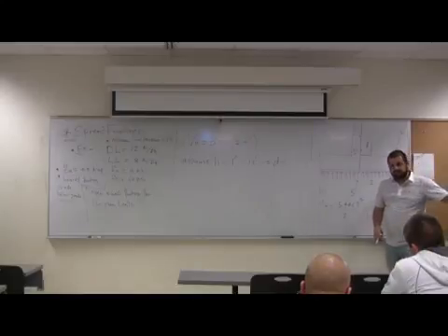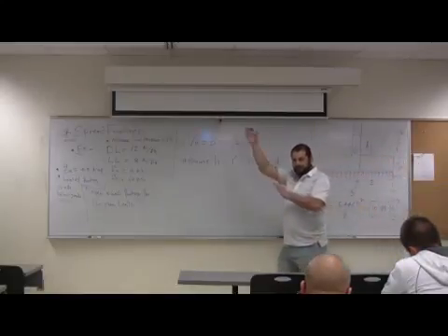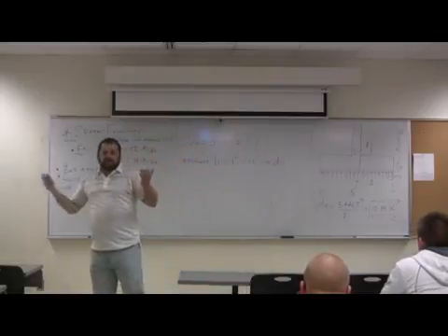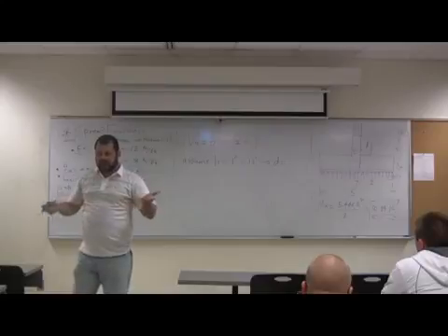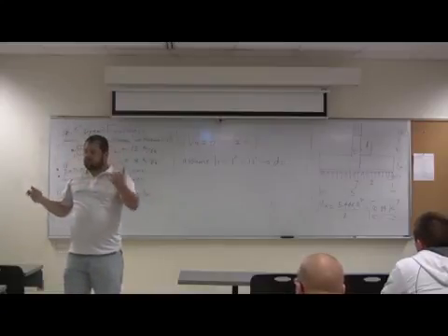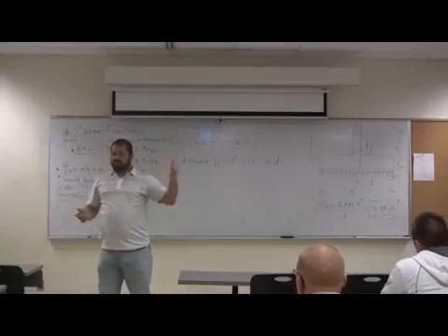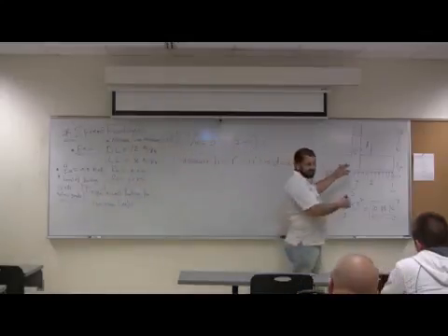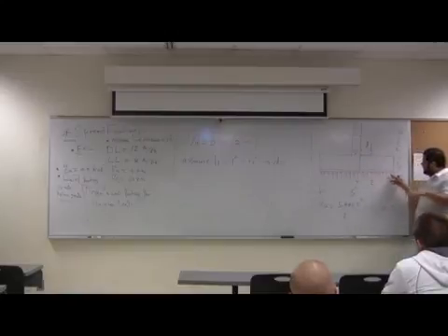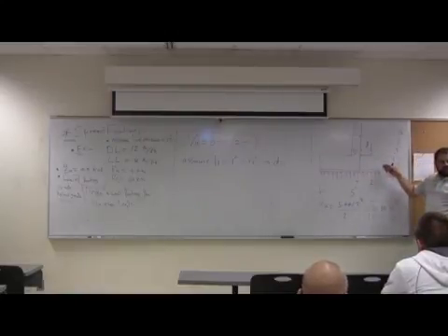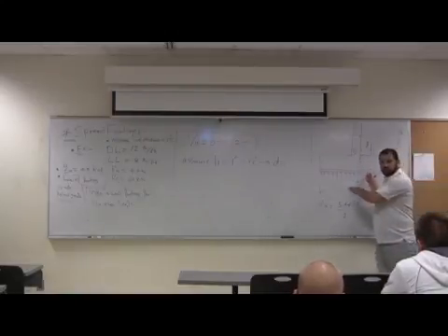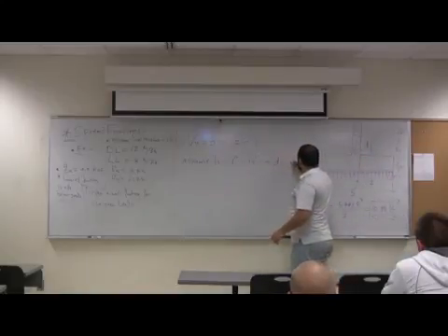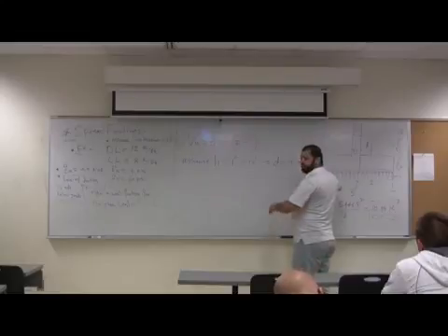It's not 4 actually, to the center. I know I said 4 for the single column footing, I'll tell you later why. But in this case, how much do you think? Are we going to use number 8? That's a huge size, right? Let's say we're going to use number 8. Half of that is ½ inch, right? To the center of that will be 3 plus ½ inch. So D in this wall footing will be approximately 12 minus 3.5.